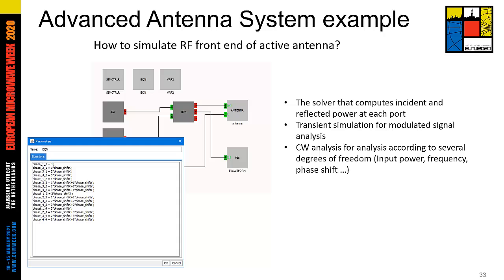The simulation is fast, so you can consider performing a large number of sweeps in frequency and power, but also apply a phase shift between the different ports and simulate the beamforming possibilities that the architectures can achieve. For example, for a 4x4 antenna, we can perform both horizontal and vertical beamforming using the variables phase shift X and phase shift Y defined by the user.